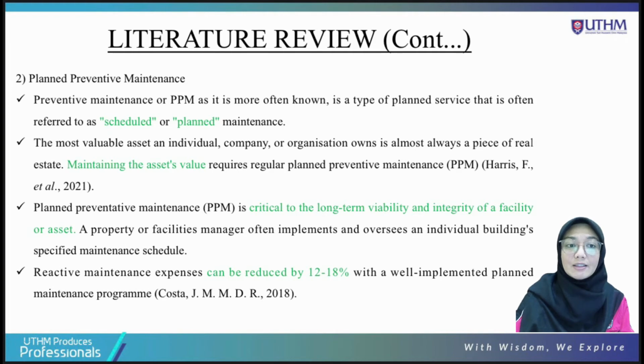Second, it is less probable that we'll have to deal with major unforeseen repairs because of frequent maintenance inspection. Third, more efficient use of labor and financial resources, as maintenance work and financial charges can be spread out more equally over the course of the year. Finally, warranty compliance, as PPM is a common warranty compliance criterion.